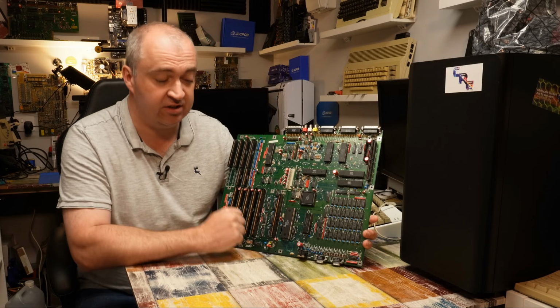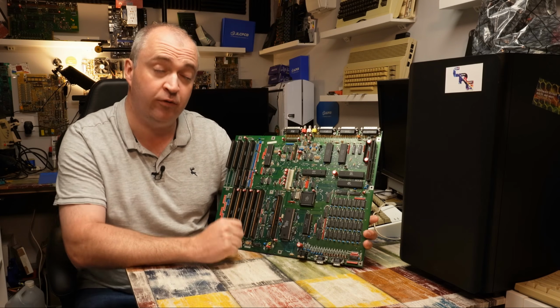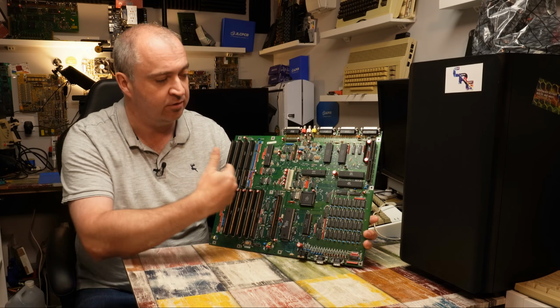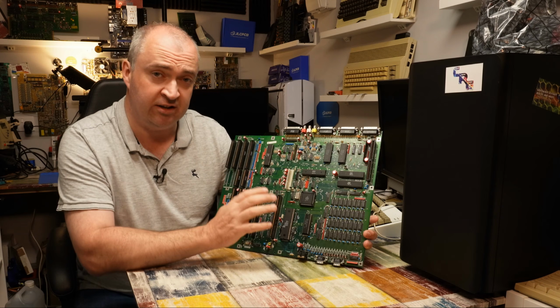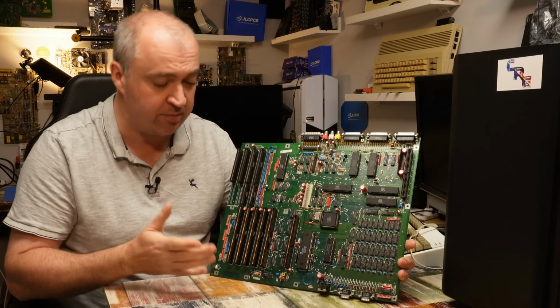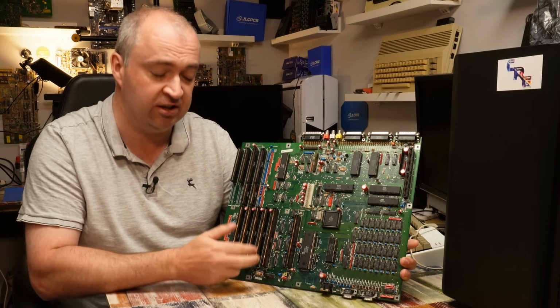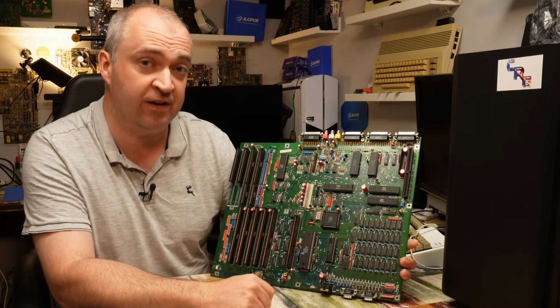Time to finish off this A2000 board. Since the last time you've seen it, it has had a full recap, one new set of red Worth electronic capacitors. We are going to try and upgrade this 4.4 to a revision 6.2. But before we do that, remember there's a problem with the Zorro slots on the real-time clock. They're not working, so let's try and fix that.